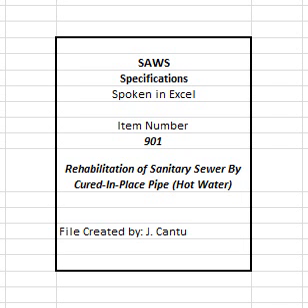C. Wrinkles in the finished CIPP which cause a backwater of 1 inch or more, or a reduction in cross-sectional area of 5% of the diameter, are unacceptable and shall be removed or repaired by the contractor at no additional cost to the owner. 1. If a void between the wrinkle and the pipe exists, the contractor shall repair or replace that section of the pipe at no additional cost to the owner. 2. Methods of repair shall be proposed by the contractor and submitted to the engineer for review and approval.